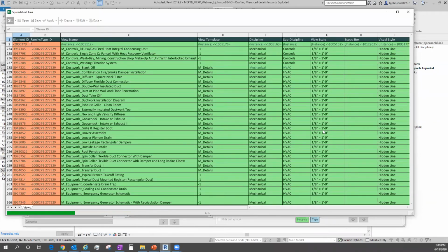While it's doing that, I also have view scale here, so I'd probably want to dive down through my view scales and find out if there's any view scales that I didn't want. Like if I see a 1 to 100, that really better be a site plan and not a detail or an overall plan or something like that. So being able to do these checks quickly and then sort on any category or any column so that it sorts up or down. It's very easy to see some low range or none or negative numbers at the top or something like that versus the higher end number at the end, or a naming convention that doesn't work or something like that. Almost finished.